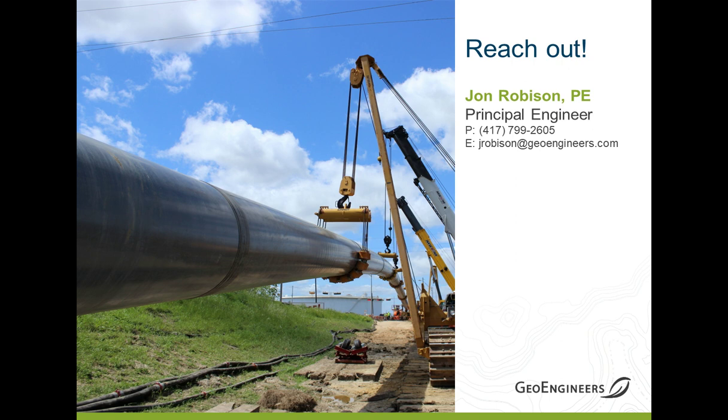Okay, and what's the best tolerance for installing gravity lines with direct pipe? For installing a gravity line, I think I would tend to be pretty tight on the tolerance, and perhaps in the spec have a pipe must slope to drain sort of a note.